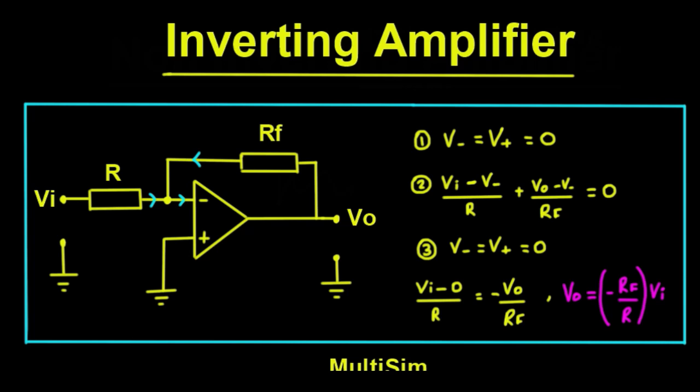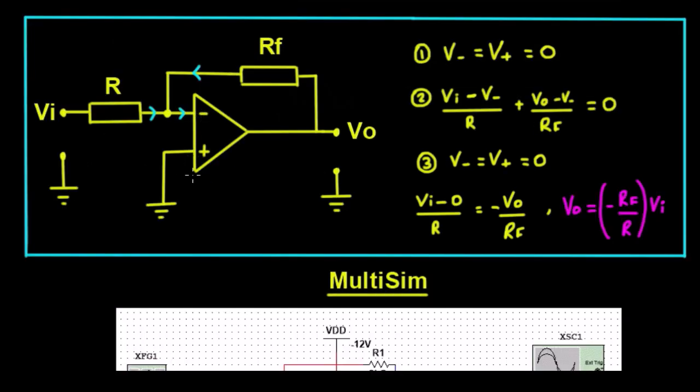In this video we're going to look at the inverting amplifier. So we've got the circuit drawn down just here, and you can see that we have the op amp sitting, and in the inverting side of the op amp we've connected up a resistor, and there's a feedback loop here to the output through resistor RF.